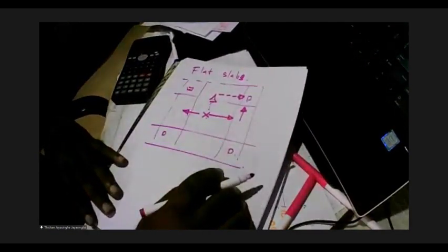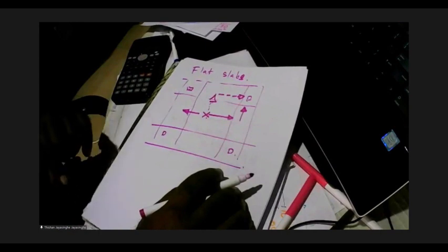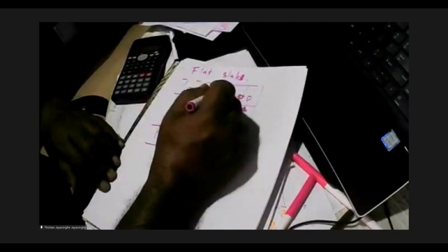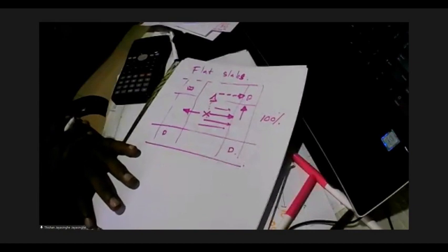So almost 100% of the load should be carried in each direction. So here you get the load transferred here and carried this way, and then part of the load will be transferred to this column strip and then carried this way. So in each direction, 100% of the load can be carried.